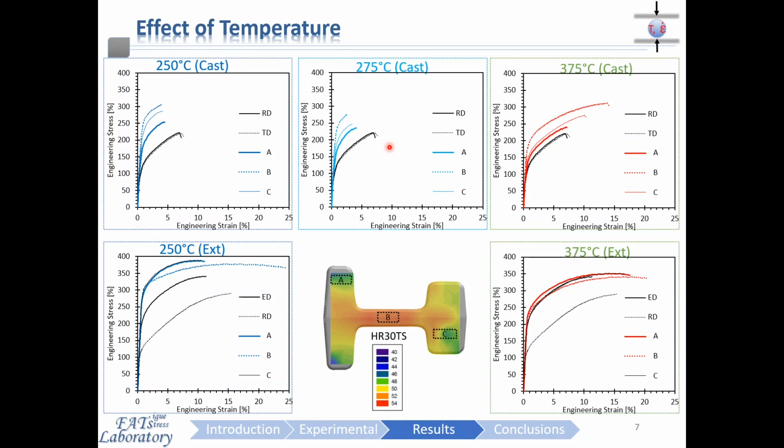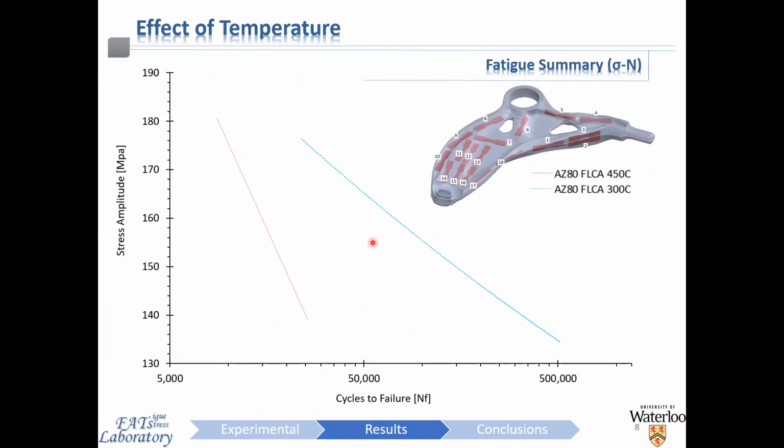Linking that back to a previous observation, the superficial hardness correlates well with the yield strength of the material in various locations throughout the cross-section of the forging. As you can see, location B generally has the highest yield strength, which is this center region that has the highest amount of strain due to forging, and it has the highest amount of superficial hardness. The other important observation is how the base material is modified due to forging. There's a much more pronounced improvement due to forging with the material when you start with as cast material, whereas the improvement with wrought material as the base material, being the extruded material, is more marginal, as one might expect.